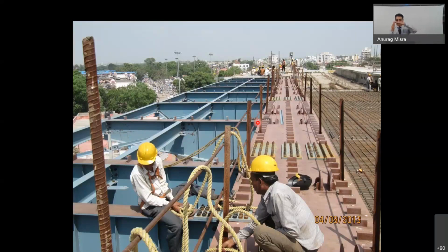Now the cantilevers have come on top, and then we use sacrificial shuttering for this, and then reinforcement is put and the casting is done. So it's a very fast construction, and probably it would have been very difficult to do this construction without disrupting the traffic on the flyover. So that is how we can actually harness the advantages of the pre-engineered structures, the advantages of dealing with the design and fabrication of structures.